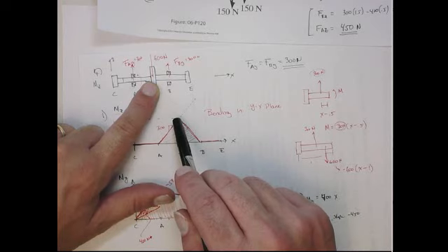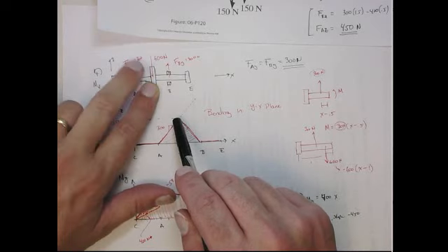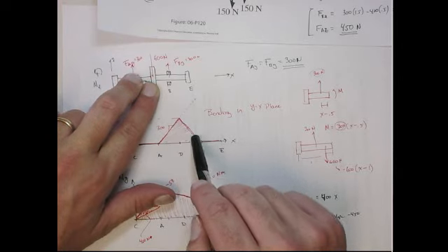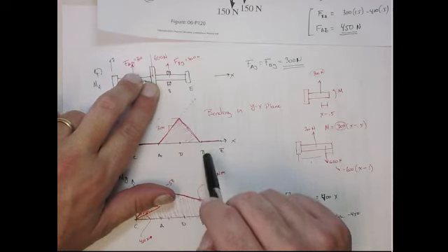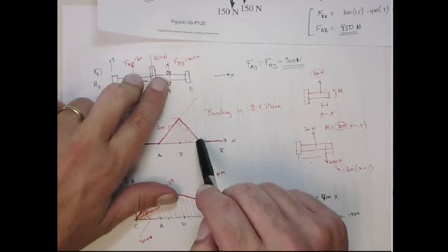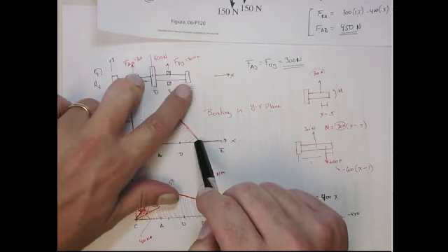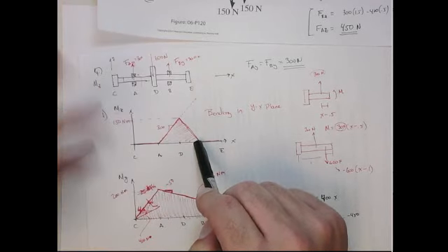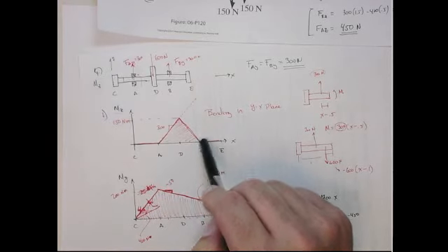That's going to give you a minus 600 plus a 300. So the net slope is going to be minus 300 until you get down to B, at which point from B to E, the net force is going to be 300 plus 300 minus 600. So that's 0.